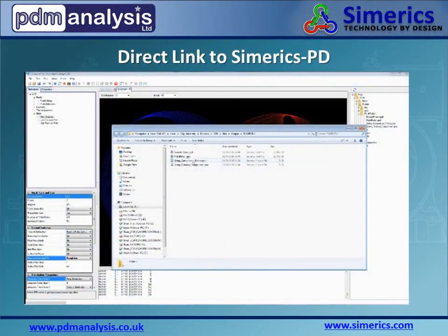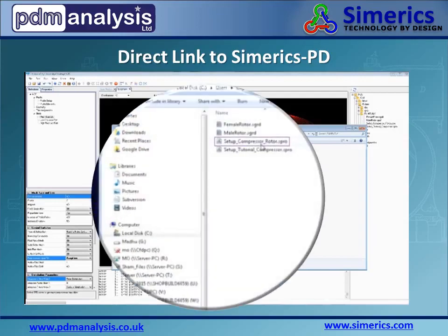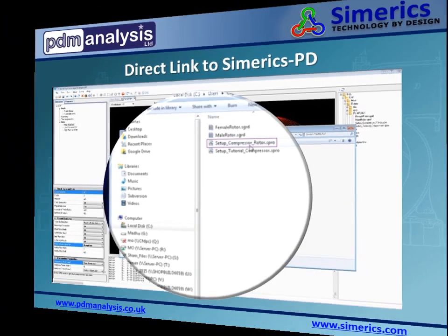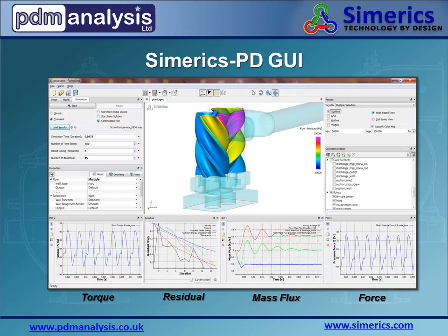After the mesh has been created, the working conditions are specified and SCORG's pre-processing scripts are used to create the necessary files for the direct link to start Simerics-PD and run your simulation. Within a couple of hours, Simerics-PD provides a converged solution with all of the relevant engineering output that you would expect from a hardware test.